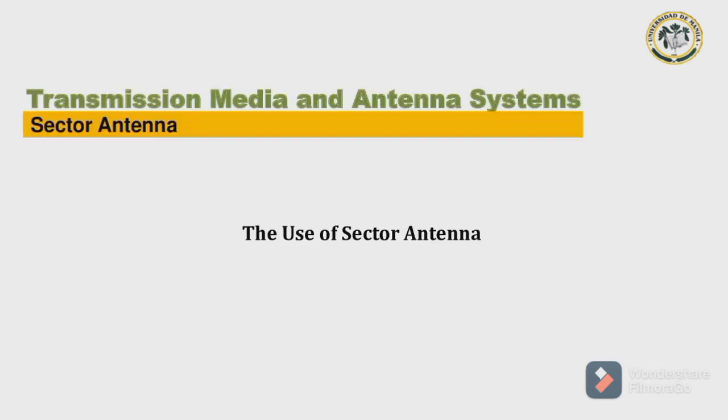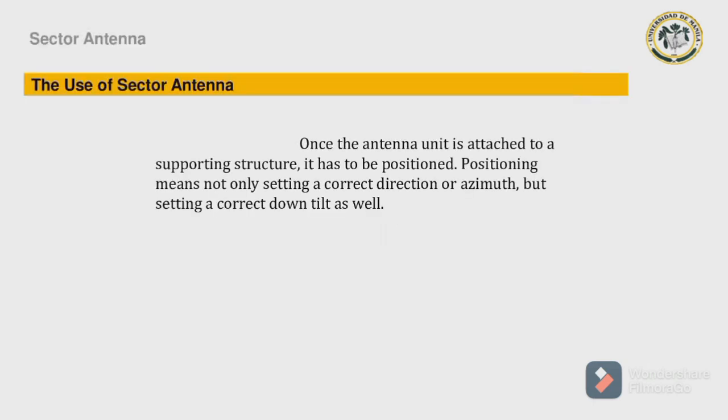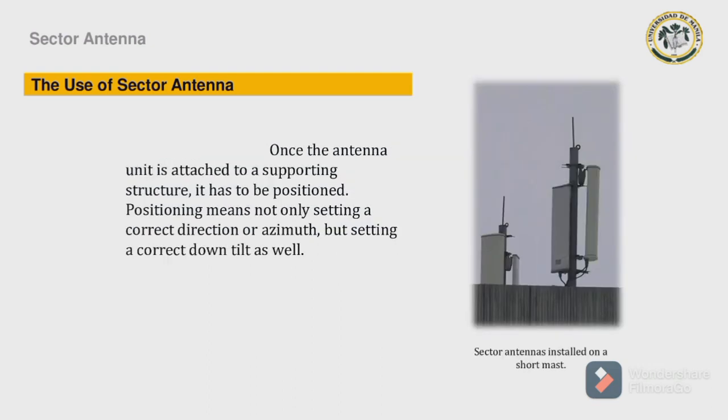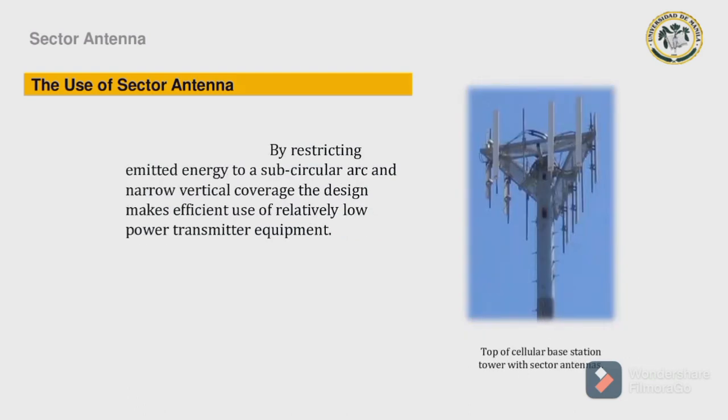The use of sector antenna. Once the antenna unit is attached to a supporting structure, it has to be positioned. Positioning means not only setting a correct direction or azimuth, but setting a correct down tilt as well.